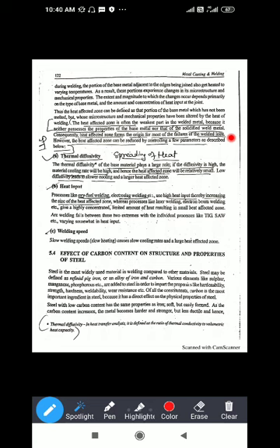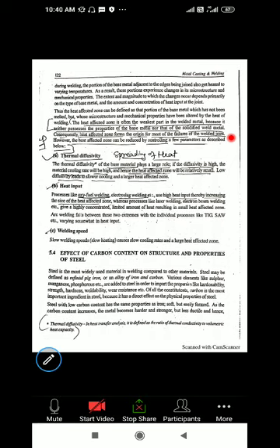If the speed is slow, the maximum heat is released there. If you increase your speed, the minimum heat will be released, and in minimum time the maximum metal can be melted. After melting, the temperature will be reduced in a short time. If the temperature reduces in a short time, the solidification will occur in a shorter time.